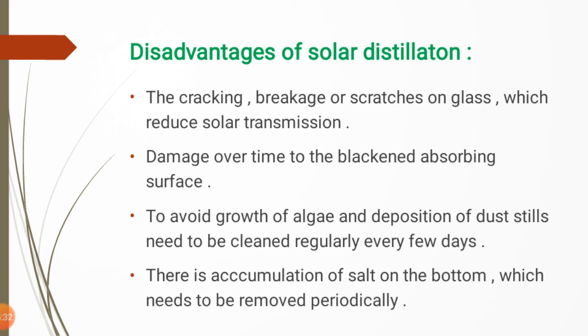The next disadvantage is that to avoid growth of algae and deposition of dust, stills need to be cleaned regularly, every few days. That means cleaning is required for the prevention of the growth of algae and deposition of dust. If there is dust deposited on the upper transparent cover, we get less solar transmission, or there is some growth of algae whenever we do not clean it regularly, every few days.